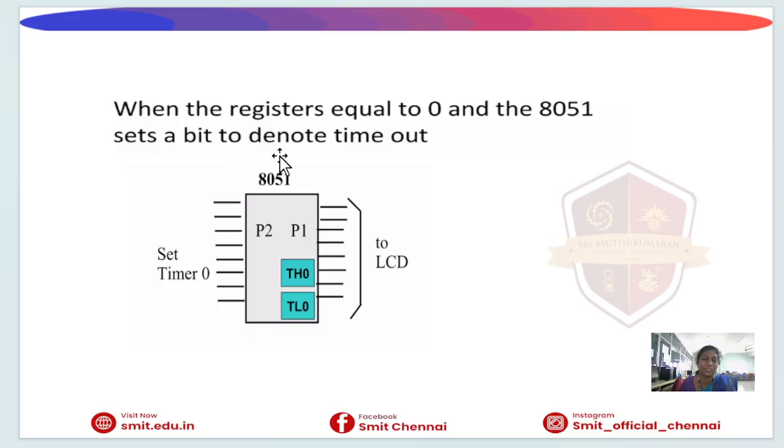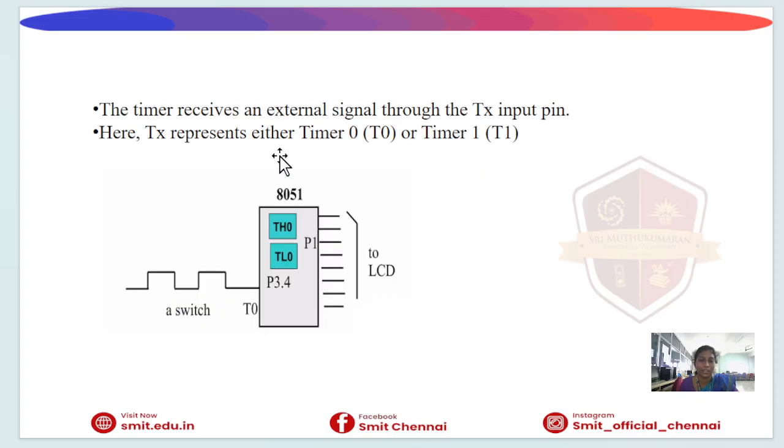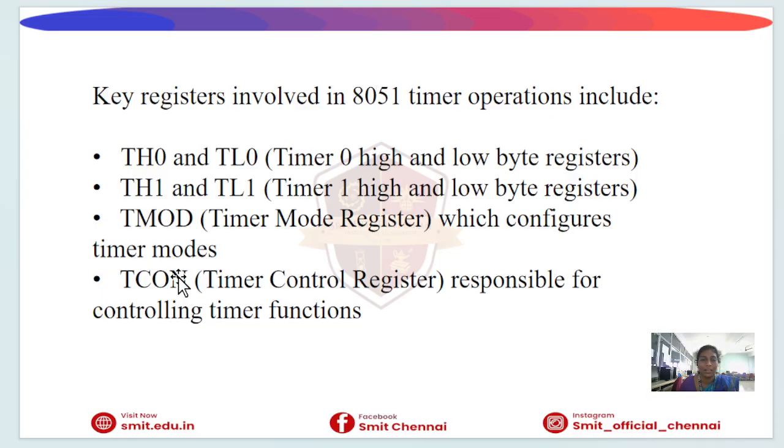The next one is the external signal through the pin. The notation Tx refers to the pin: T0 for Timer 0 and T1 for Timer 1. The external pulse increments the counter. So the microcontroller can read the count and take a decision based on the result.